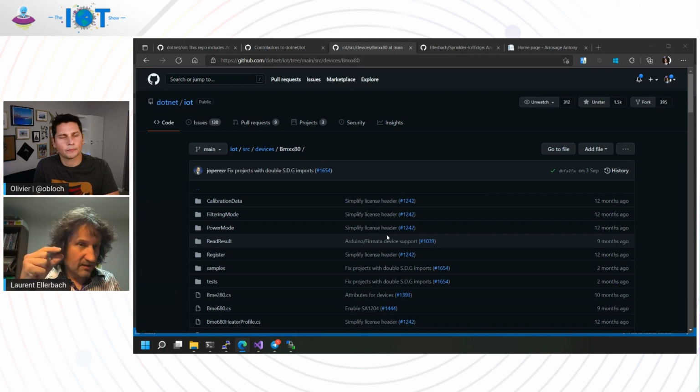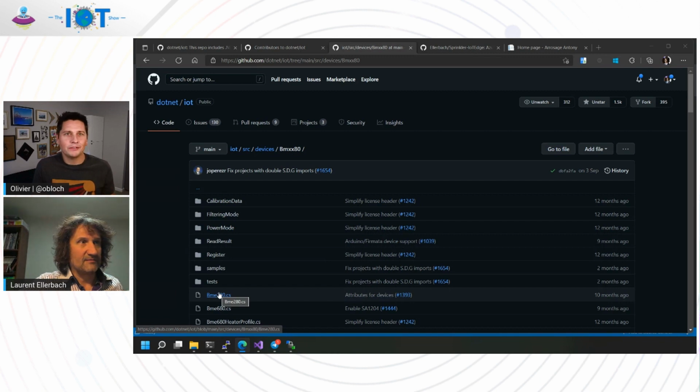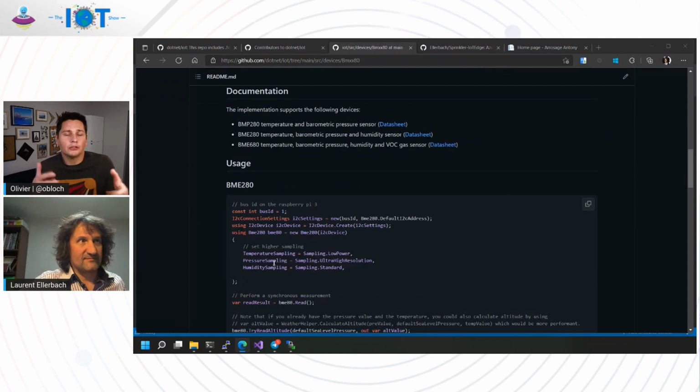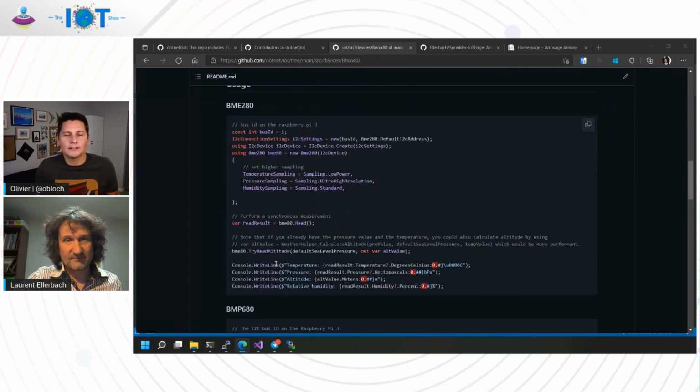You just need a way to get those little connections for the T part, and we'll cover that as well in a demo. Yeah, because accessing the usual things that an embedded developer would need to know and access, the registers, the GPIOs, I2C, SPI, all these acronyms that lots of .NET developers might not even know about, are things that are required to access hardware with specific field buses, specific connectivity that is not USB, that is not provided by the OS by default.